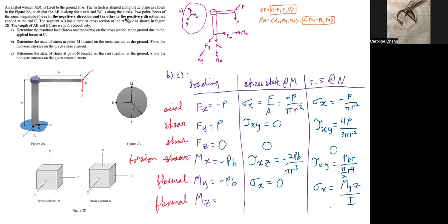So the moment around the y-axis will be given by negative PB, but because we decided to add the negative sign afterwards, we have to make sure to take the absolute value of My, because we are determining the sign using observation of how the beam bends.